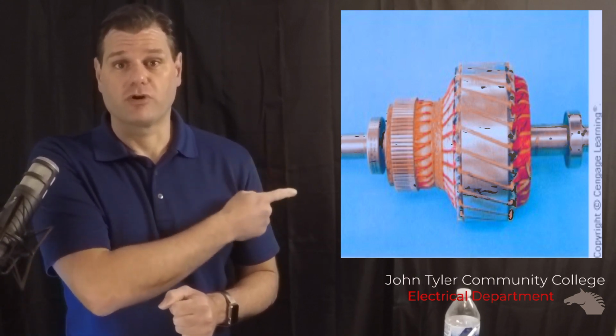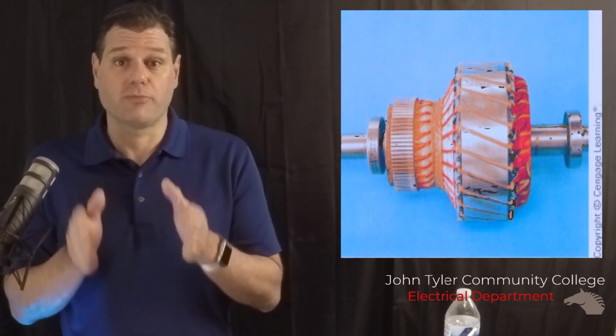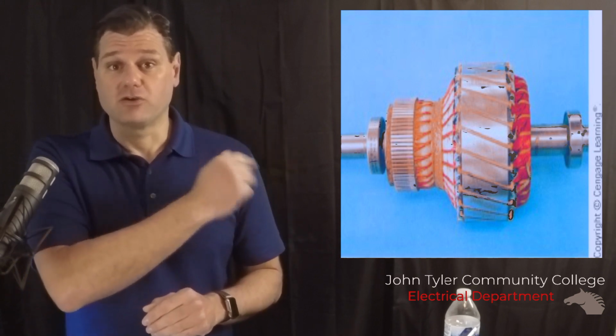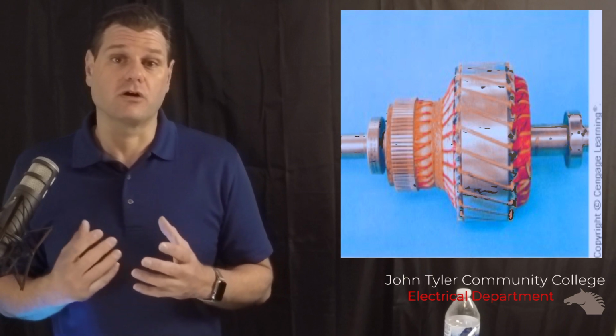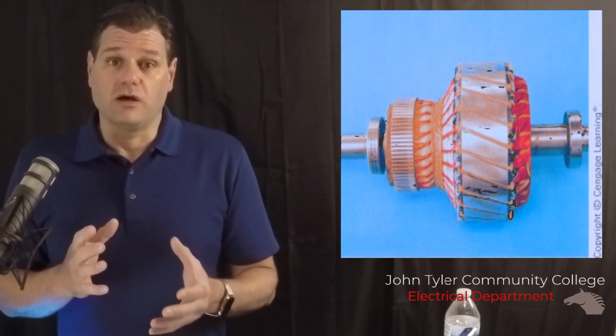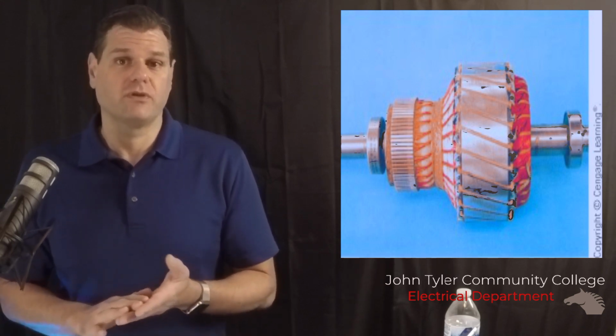This is the part in the corner here, the copper looking thing with the lines cut in it. That's where the commutator is, and those are the pads for the commutator. Beyond that is the core, and then you see the little red wires. Those are your conductors, your wire. Now, the reason they're red is because they have an insulator, like a resin, on them.